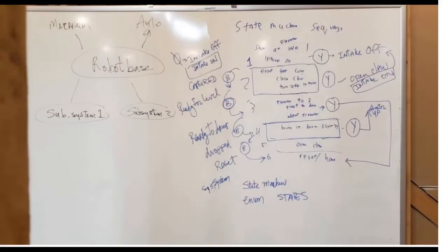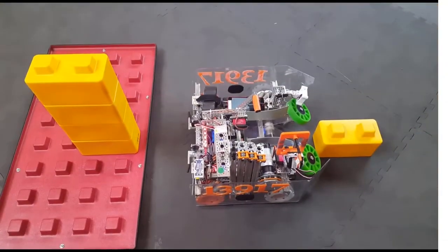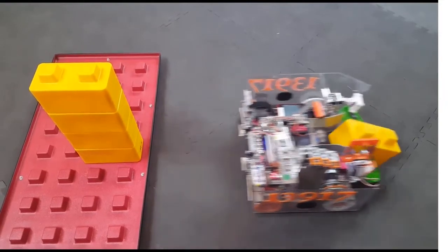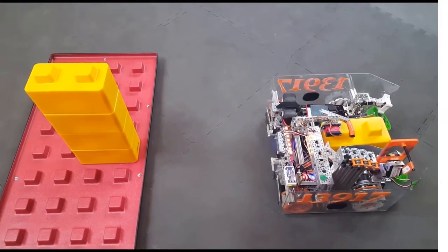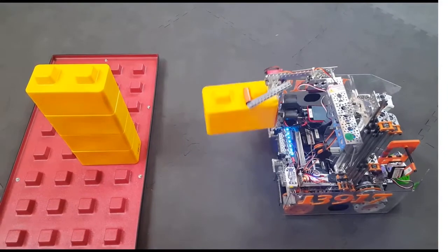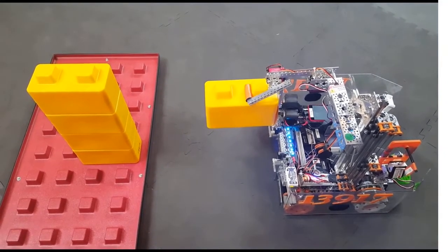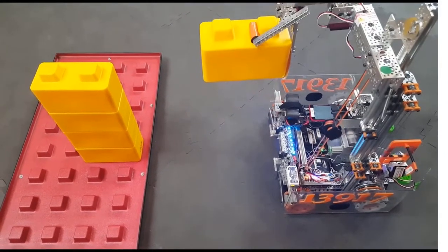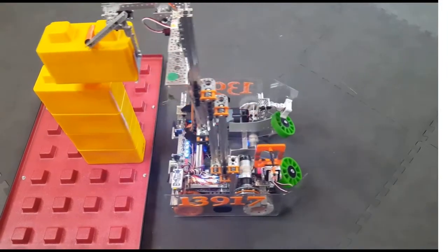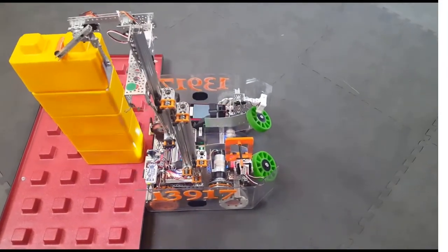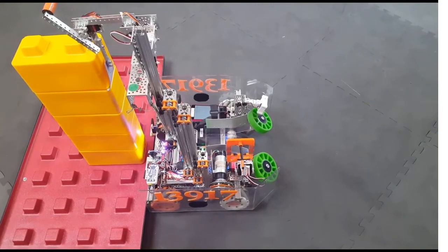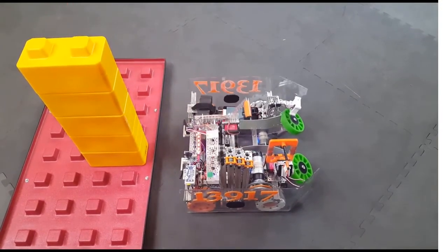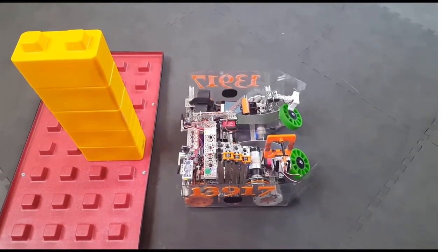Next, we ran several 2-minute-long teleop cycles. We recorded the sequence of buttons pushed to pick up the stone and stack them. The sequence is: turn on the intake, drive forward into the stone, close the claw, elevator up so we don't hit the side of a robot, pivot to the drop position, elevator up and down to align it to the correct level, align the stone over the tower, lower the stone over the tower, open the claw, home the pivot, and home the elevator. Using this information, we created a finite state machine.